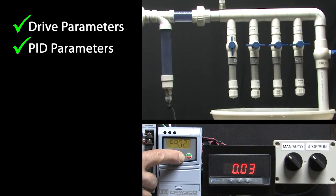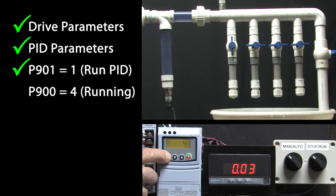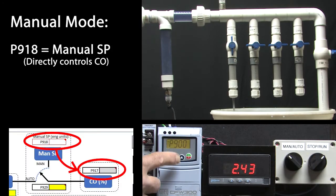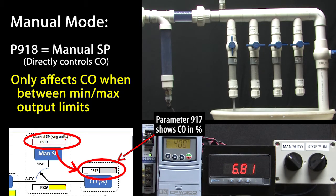Okay, let's go to parameter 901 and set it to a 1 to tell the Soft PLC PID app to run. I'll go to parameter 900, and sure enough it's a 4, which tells us the PID app is running. Well, we're in manual mode, so I'll go ahead and switch to run, and I'll go to parameter 918 and scroll through some values. Remember, we set the min and the max motor speed to 25 to 50 Hz. So while we can set the manual set point to whatever we want, it won't actually do anything until it's between those 2 frequencies. If I go to 35 Hz, and sure enough the pressure is near 7 psi, exactly what we expect to see from the plot we created in the previous video.